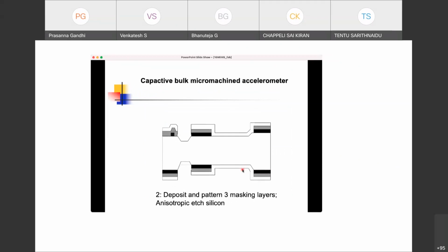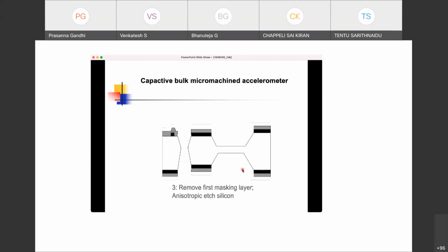Okay, now this is an accelerometer. The basic fundamental idea is that similar processes are repeated again and again to create these different cavities and shapes, and you get this accelerometer, in this case by bulk micromachining. So this is an etching that you carry out in such a way that this cavity gets open, but a cantilever beam still remains, and a big mass for the accelerometer that is needed, which is there from the base silicon material itself. I mean the wafer material itself.